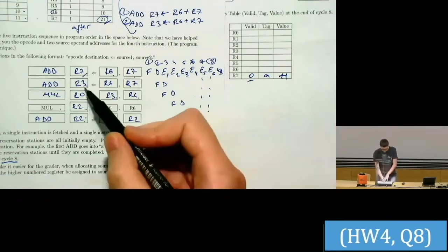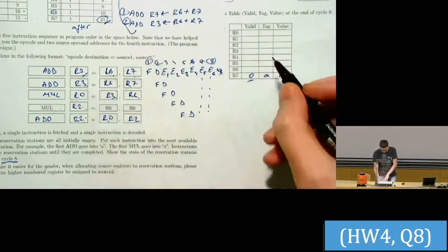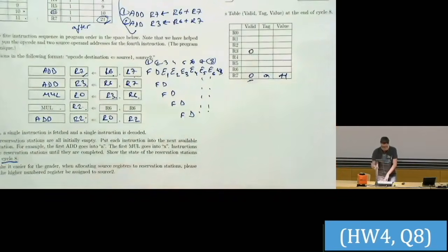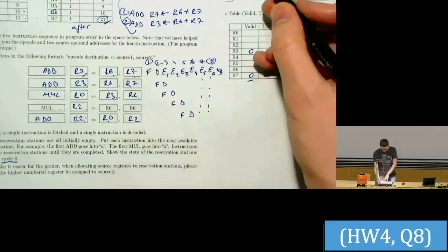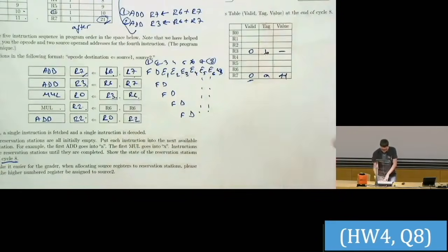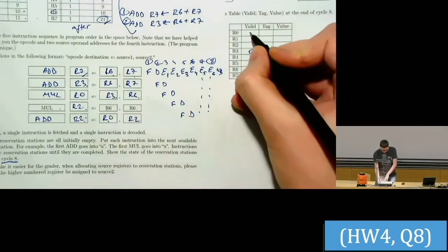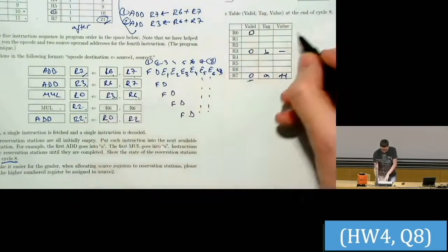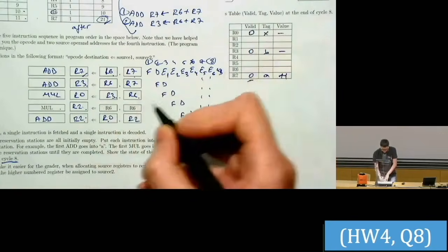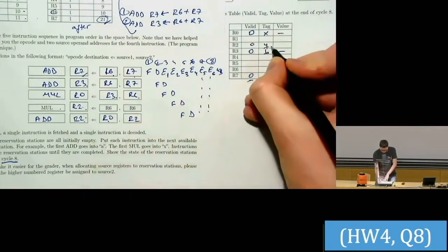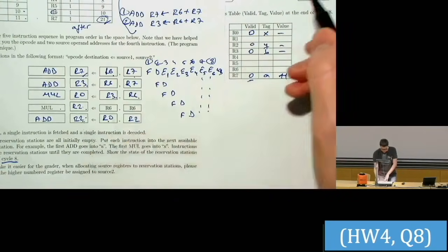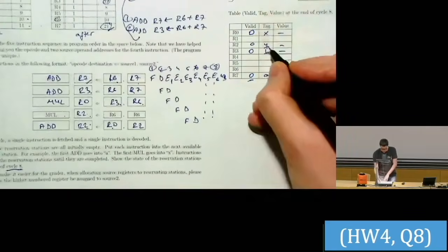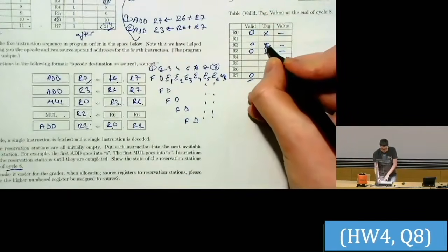Okay, and then the next register we update is R3. So for R3, again, we will have 0 because none of the operations are committed until end of cycle 8. And it is allocated to B. Okay. And then R0 is again not valid, and then it's allocated to reservation station entry X, R2 is allocated to Y, and R2 is again allocated to C. So here you basically update this again, okay?